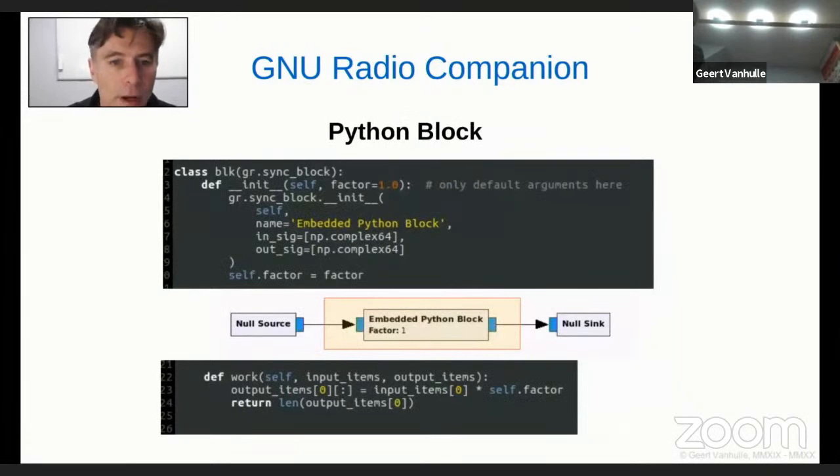Inside the Python block, we can define functions to process the samples any way we like. We have here a list, a complex list of NumPy, so the Python NumPy library, complex NumPy lists. And this list we can process, do, for example, multiplication, then we create the same thing as the constant multiply block. And we have an output list that is actually putting the output samples back into the flow graph stream.